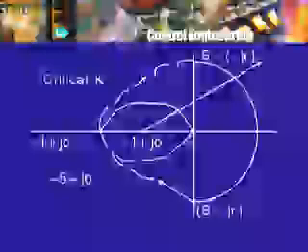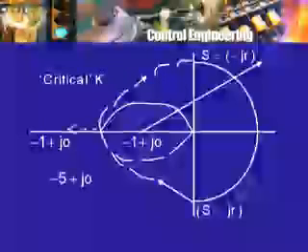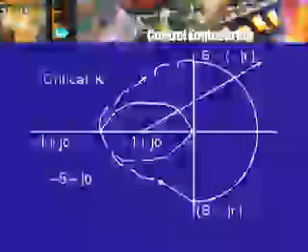And of course, if the phase shift is very large, and if the particular system is such that with that large amount of phase shift, this diagram turning may even pass through the point minus 1 plus j0. So the system will become unstable because of this unforeseen phase shift introduced by the amplifier. And therefore, one may specify a certain amount of phase margin for the design. That is, you should stay sufficiently away from the point minus 1 plus j0, both with respect to a change in gain and with respect to a change in phase shift.